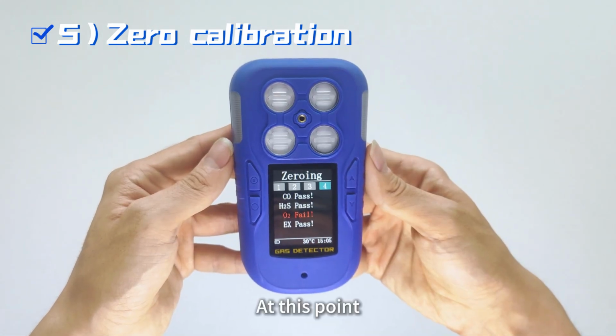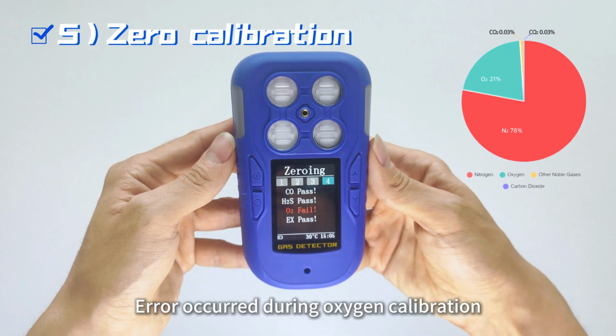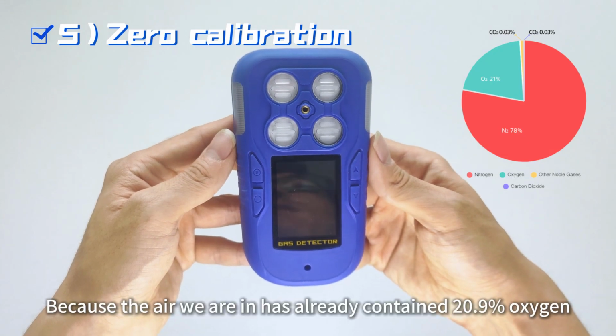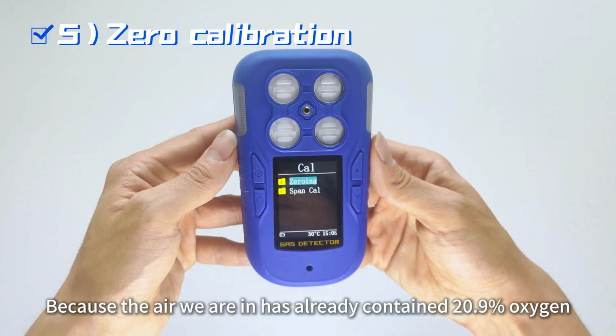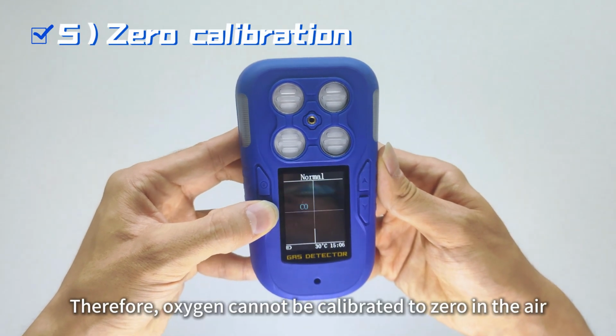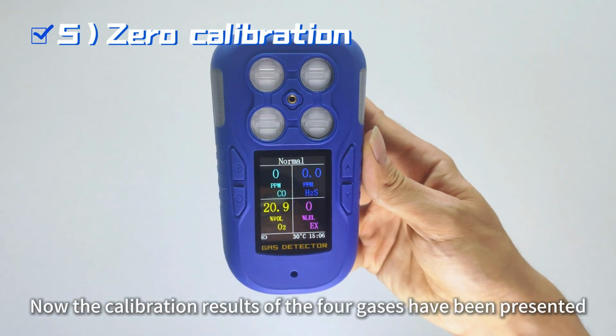A calibration time of 70 seconds is required. At this point, the calibration results of the 4 gases have been presented. An error occurred during oxygen calibration, because the air we are in already contains 20.9% oxygen. Therefore, oxygen cannot be calibrated to 0 in the air.